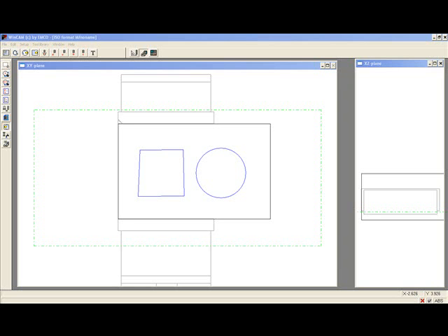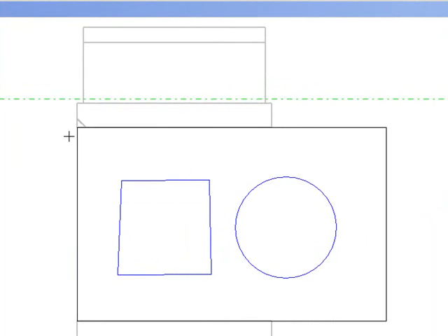During this demonstration, I'm going to show you how to program the CAM functions for pockets with islands. This is the first of a couple of different ways to do it. You also have pockets with no islands, which we're going to cover in a little bit different demo. So for this one, pockets with islands, I've purposefully left out a specific geometry.